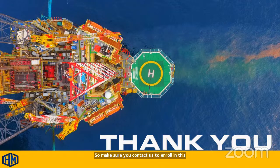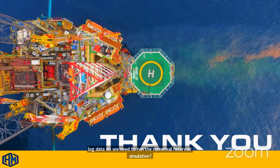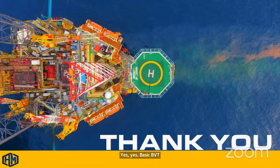We have one last question: what PVT and log data do we need to run the numerical reservoir simulation? Yes. Basic PVT parameters, if you define a black oil model, in that case are oil formation volume factor, solution gas-oil ratio, oil viscosity, and also oil density. This is the minimum PVT data required for a black oil model.